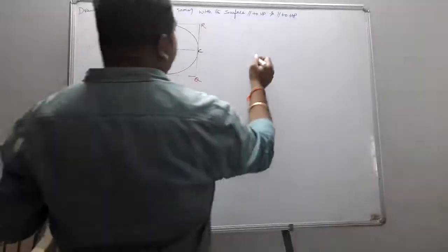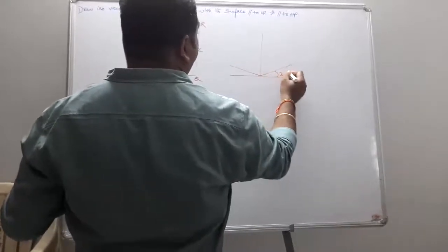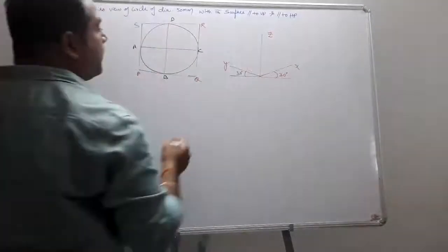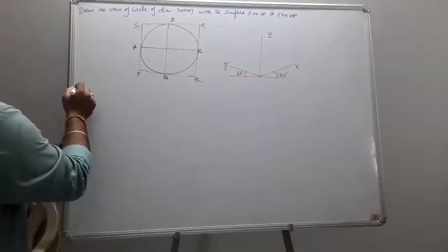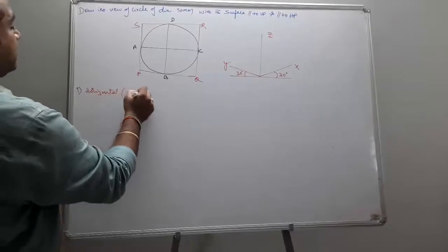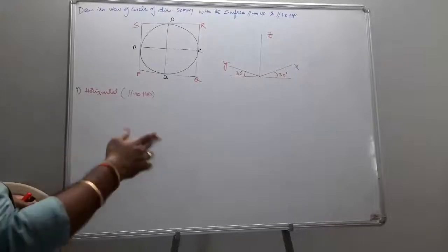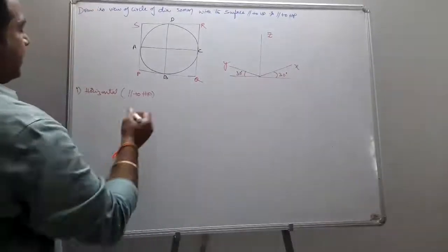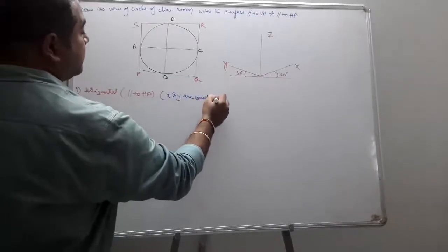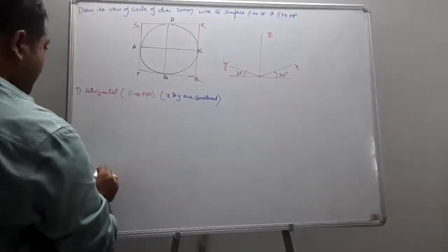And I know the isometric axis was 30 degrees, X, Z, Y. So first of all, I consider horizontal. Horizontal means parallel to HP. When parallel to HP, which axis is considered? Horizontal is X and Y. So X and Y are considered.